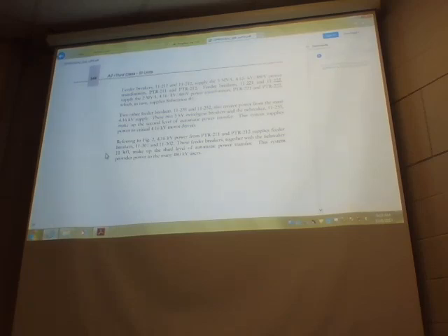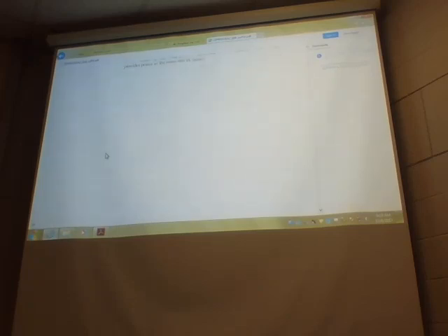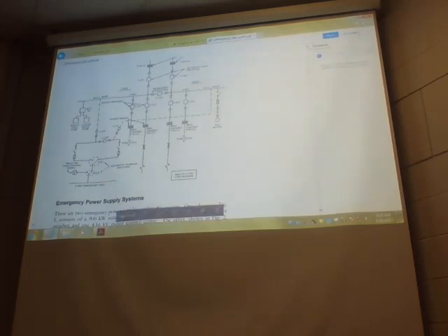Now we're down. 11221 is here, and it needs this transformer, PTR 221, 4160 volt, 480 volt, 2 megavolt amps. So it's a step down transformer, and that goes to substation number 1. Feeder breaker 11211 then feeds PTR power transformer 211. It's also 4160 volt, 480 volt step down, and it's rated at 3 megavolt amps.